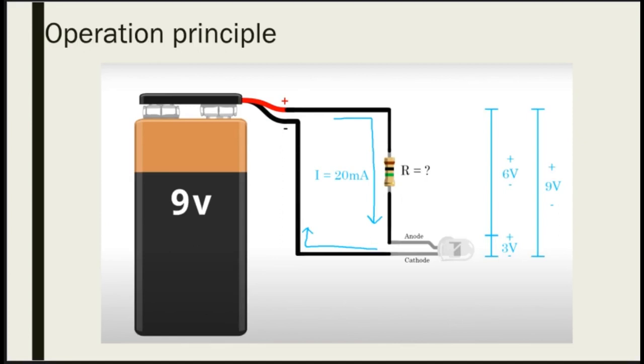Okay. So as you're finishing up, what information do I know so far about this resistor? What was the first thing we figured out about it? How much voltage is measured across that resistor? 6 volts. And Ms. Hamidi then gave you the information of how much current is flowing through. 20 milliamps. So what can we figure out now about the resistor? I know the voltage across it. I know the current through it. What's the only thing left to actually figure out, Eva?